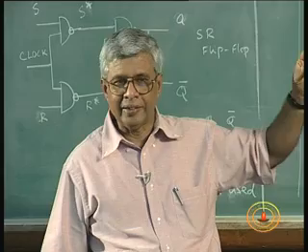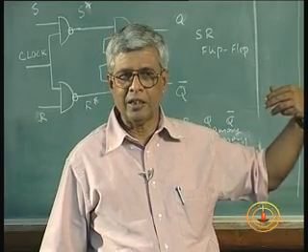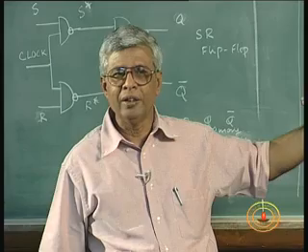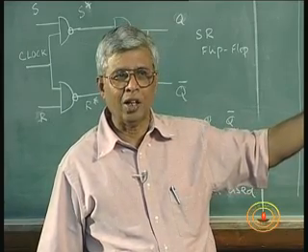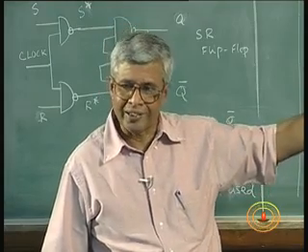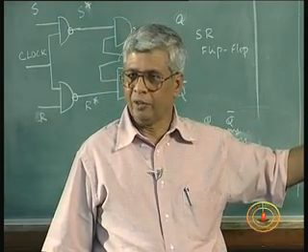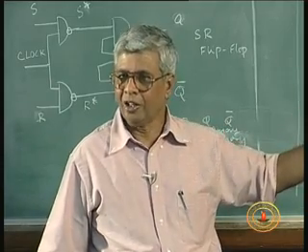It depends on the clocking, the circuitry, no. But the problem in this case is, since the clock is going to be controlling the whole operation, the clock is going to be the time at which the circuit is going to start working. It does not matter when you put S, when you put R, as long as both are before the clock becomes high.